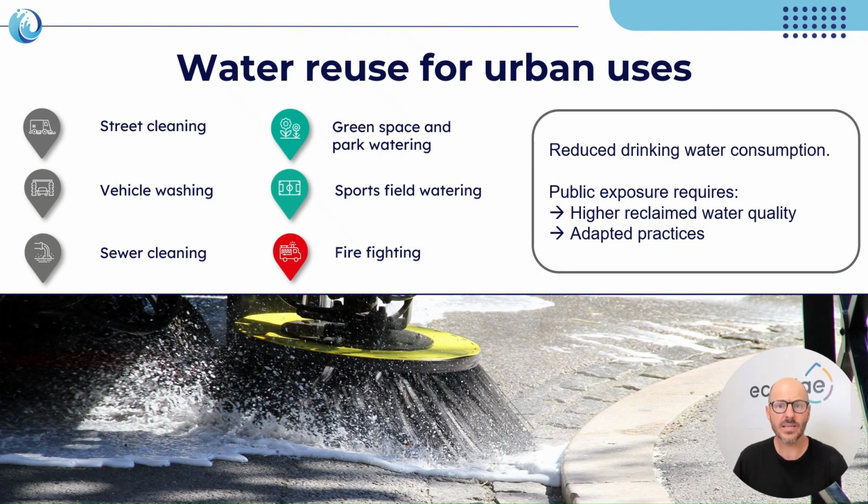Most of the wastewater comes from the city, so it makes sense to use it within the city, thus reducing drinking water consumption. Urban uses such as watering of parks and green spaces, street cleaning and sewer cleaning become logical uses for reclaimed water. However, given the urban context and the risk to the general public, the quality of the recycled water generally needs to be higher than that required for irrigation.